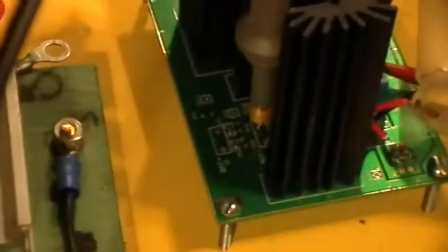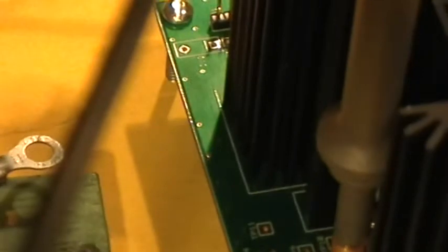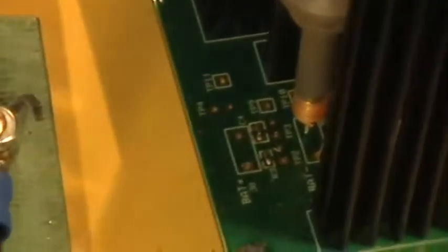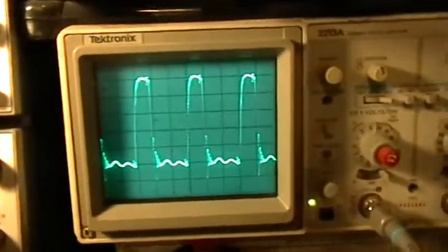And here I'm looking at the voltage across the current sense resistor with this special probe, master probe connector there. That is a minimum inductance probe connection, and this is what the current trace looks like.